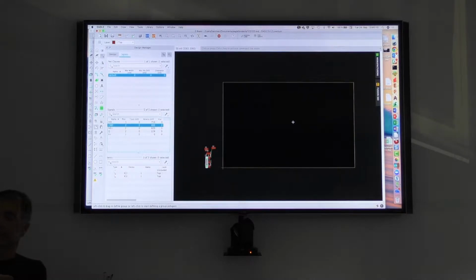So if I name the layers 1, 2, 3, 16, I have drills from 1 to 2, from 16 to 3, and I have 1 through the whole stack from 1 to 16. If I would build it the other way around, I could have drills from 2 to 3, and then through the whole stack, so there's a difference in manufacturing, in options now. And that's something you have to know in the beginning.